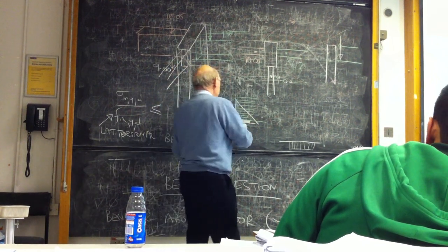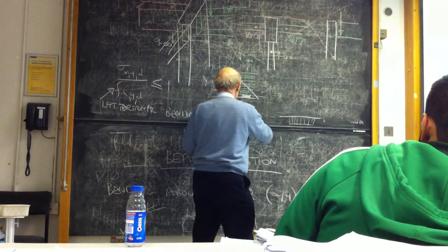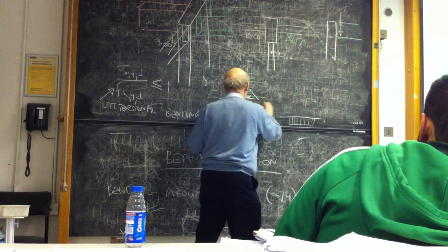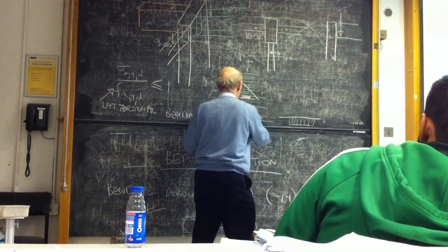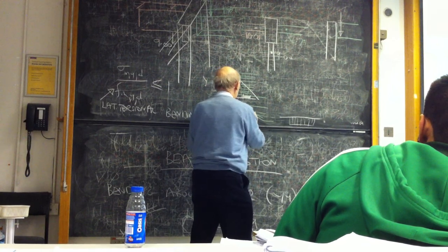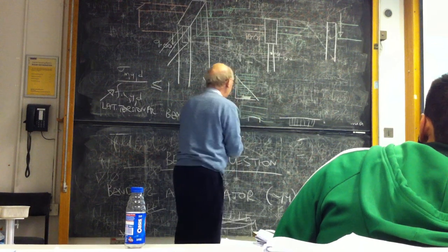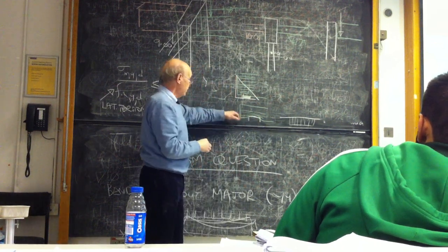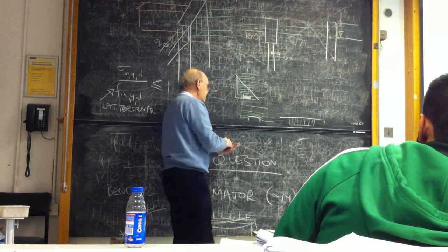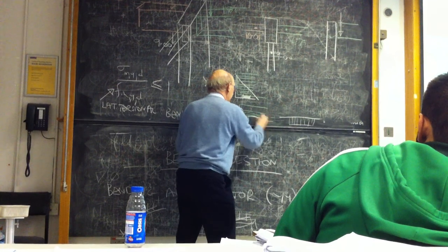What the code says is that the timber beam will eventually, as it were, crush something like that, where that's the platform, and you can assume that because it crushes like that and has to bend these fibres, the effective area over which it's supported is from there to there.